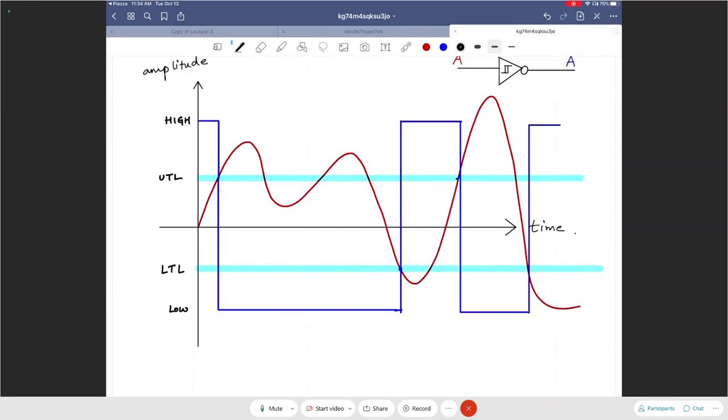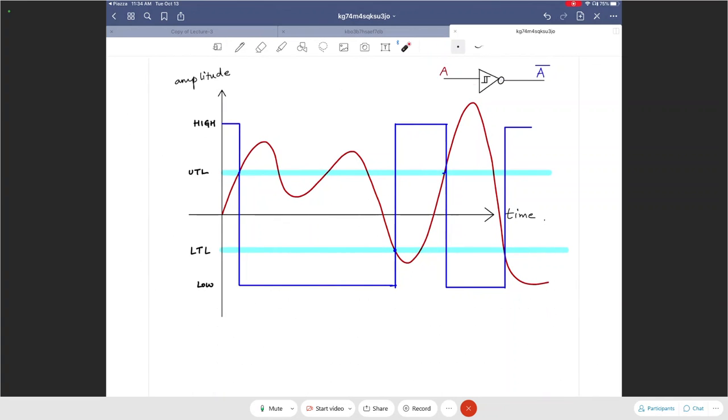Would we assume that this is the same behavior as a PMOS transistor? Oh, so this is for the complete NOT gate. This is for the Schmitt trigger based inverter. So this will have CMOS transistors, so it will have NMOS and PMOS transistors that go inside this. But the way this is designed is such that it responds to two different thresholds as opposed to responding to one threshold.